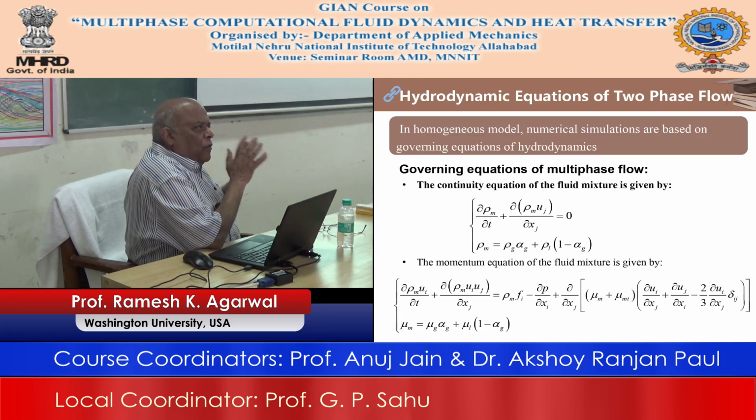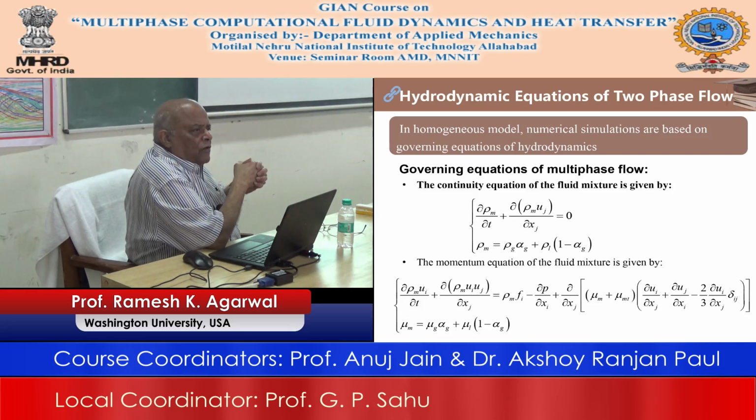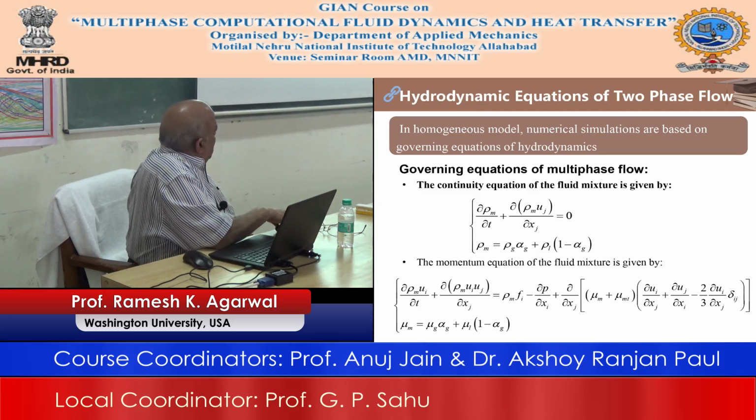And that is the flow in a rotating turbine with a certain number of blades, with liquid water entering. Because at certain places in the flow field the pressure is lower than the liquid pressure, it evaporates into vapor, and that causes the cavitation. We will assume that all the bubbles coalesce or whatever happens, and they form the air pocket.